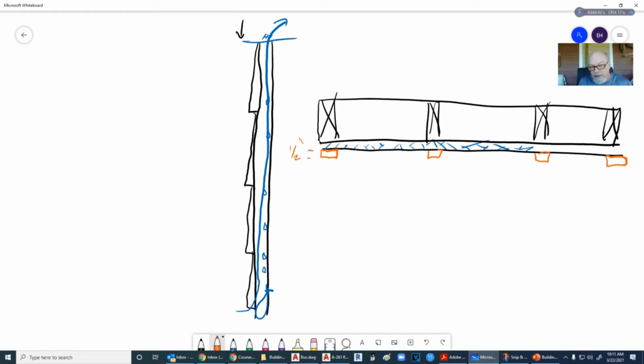Because they're a half inch, I stand a problem of them splitting. And that's what I've had a problem with. And then I'm going to put my siding on there, and I'm going to nail it on as well. So now I have two nails going through a very thin piece of wood, and it stands a better chance of busting. Now, if I can get it on and everything's okay, hopefully I can get away from the job site before it falls off, right? No, I want to make sure that I do a bang up job on this. And so care has to be really taken when putting these things up.